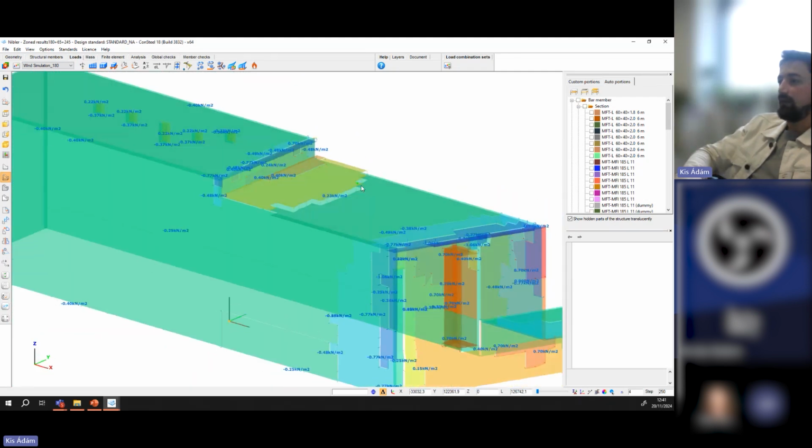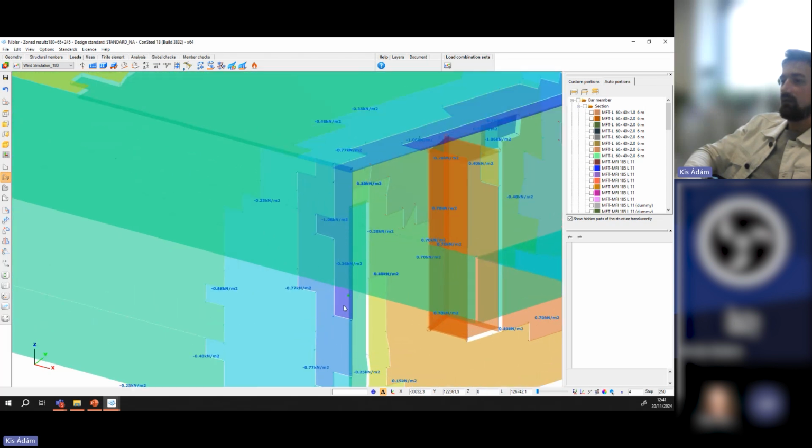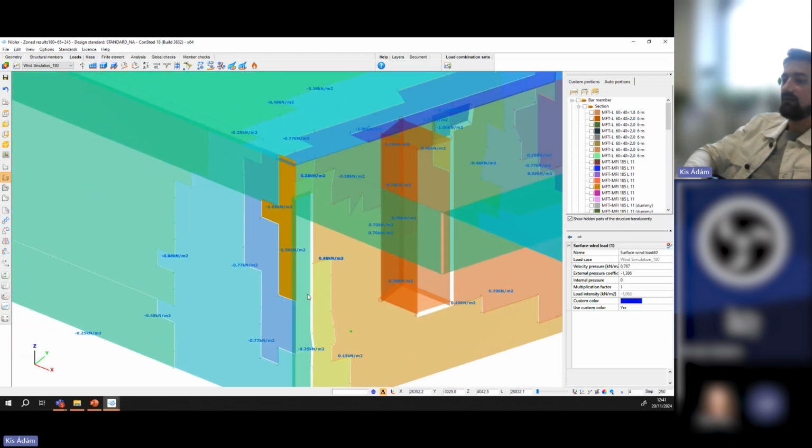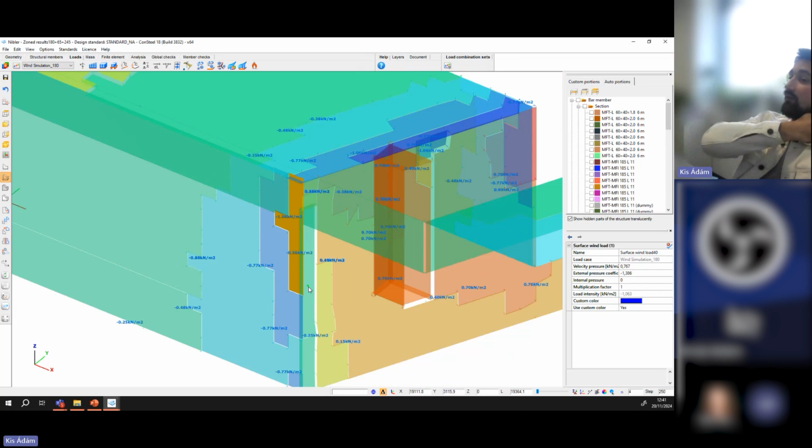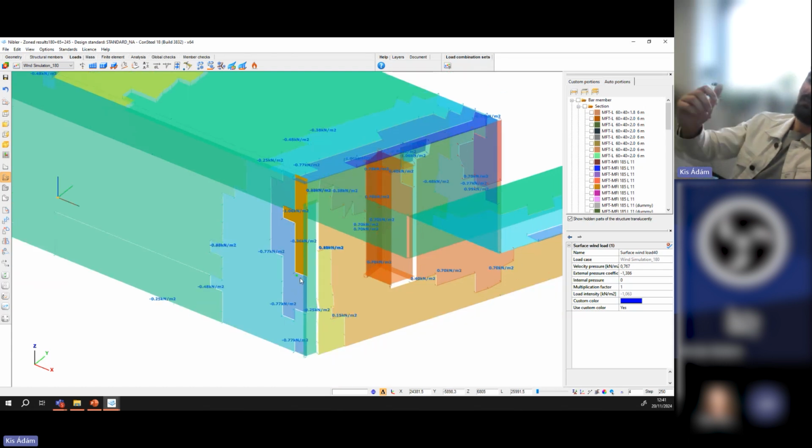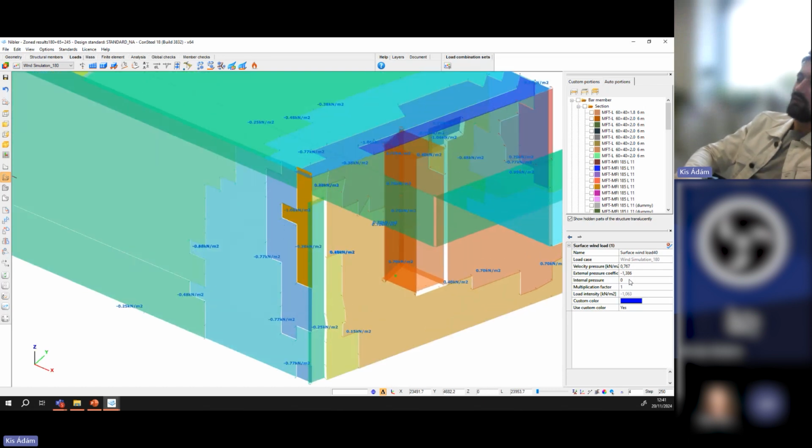We can also check, or see really easily, that we actually have 4 zones instead of 3, because simulations at a certain building height can obviously capture this distribution, where the higher part of the structure has much higher suction values. So there is an additional zone which has a higher external pressure coefficient value.